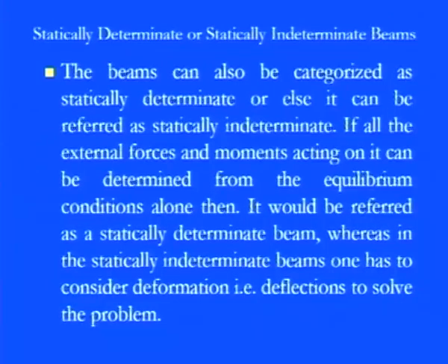And that's why we are categorizing two main ways. One, if we are talking about the statically determinate form, then our main focus is on the stress and strain, how these bending stresses are forming and what the bending moment is, and how we can calculate all these things based on the different cross sections. But if our beam is in a statically indeterminate form, then our main focus is on the deflection, and then the deflection theory comes in. So it is altogether a different chapter and altogether a different concept. So here we are categorizing the two main ways: one is the statically determinate beam, and the second is the statically indeterminate beam.